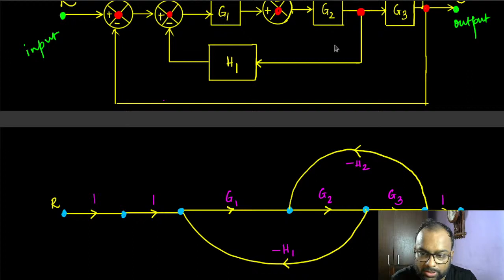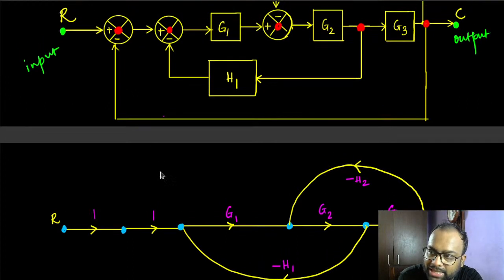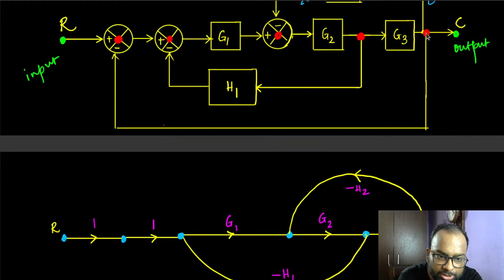All right. So we got this connection depicted here. And we have one last connection to take care of, and that's this connection. There is a direct connection out of this, from this up to this. Once again, we can write this as a plus sign here, and instead put a block that has a gain of -1.